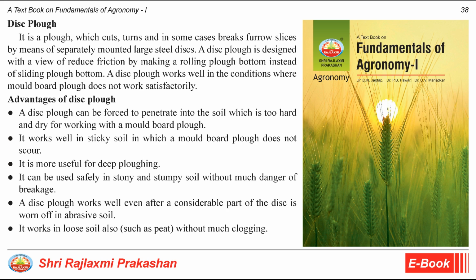Advantages of disc plough. A disc plough can be forced to penetrate into soil which is too hard and dry for working with a mould board plough. It works well in sticky soil in which a mould board plough does not scour. It is more useful for deep ploughing. It can be used safely in stony and stumpy soil without much danger of breakage. A disc plough works well even after a considerable part of the disc is worn off in abrasive soil. It works in loose soil also, such as peat, without much clogging.